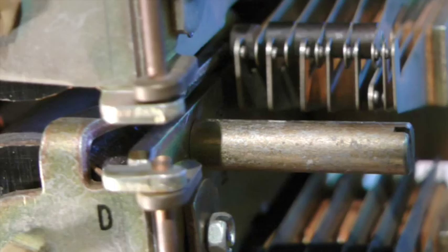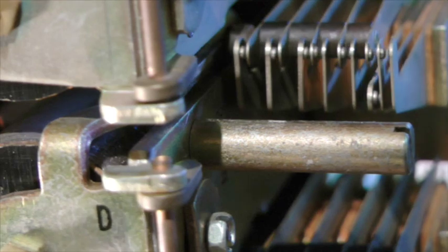If there is ground on the start lead due to a central office test procedure or a false ground condition, the D relay will remain operated and the 11th rotary step operation will be repeated on the next available line finder. If there is no ground on the start lead, the D relay releases and the idle line finder becomes available for selection.